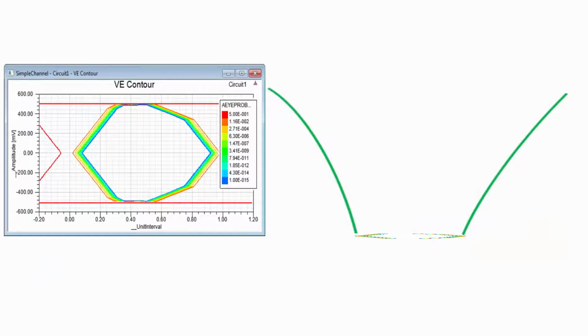A contour plot shows the bit error rates in colors, with the threshold voltages ranging from the lowest to the highest on the y-axis versus the unit interval sampling time on the x-axis. The contour plot is the view looking down into the bathtub. The bit error rate is the lowest at the center of the contour. The contour is widest at the optimal threshold voltage.